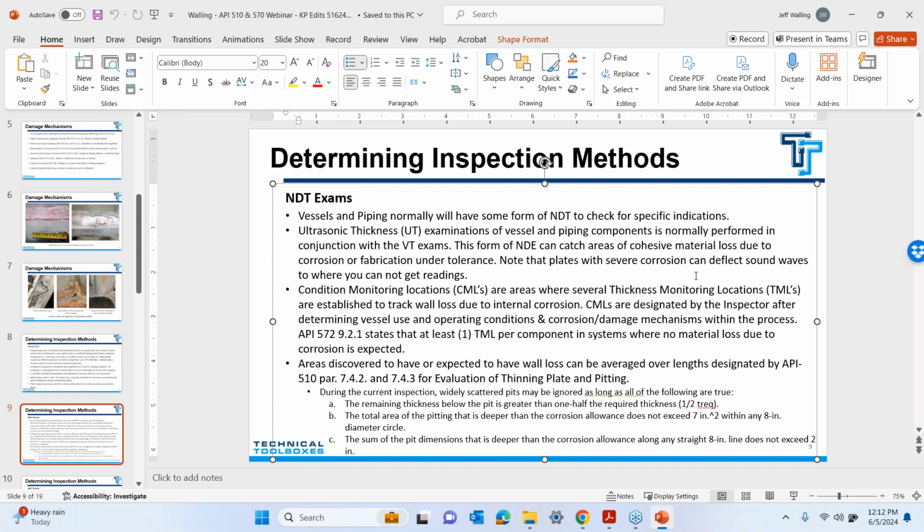All right. You might need, if you're aware that there's issues with this, there should be some little indicator on the vessel where you can take the readings from the exact same spot, so you can do long-term, short-term corrosion rates.